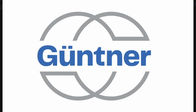Yeah, so that's a good question. Whenever the unit is ordered with just one temperature sensor, we ship that temperature sensor inside the control panel. The purpose is that we want that sensor installed in the common outlet header at least 1 foot after the fluids mix. We also ship it with a well.